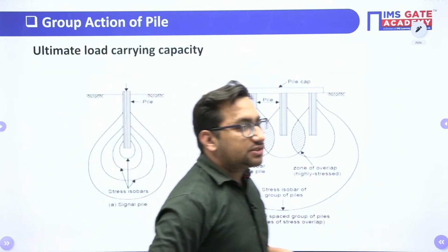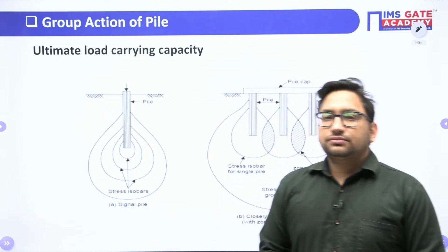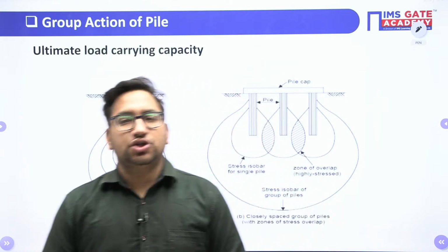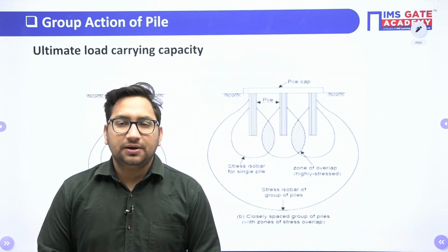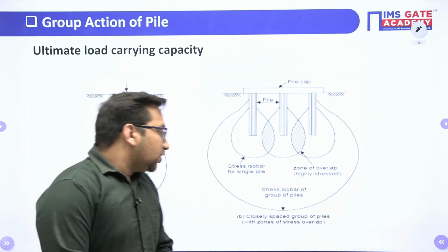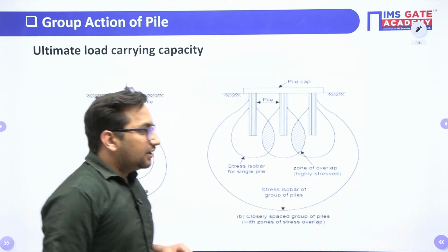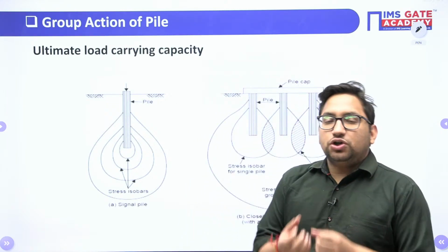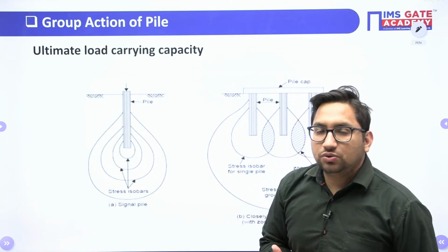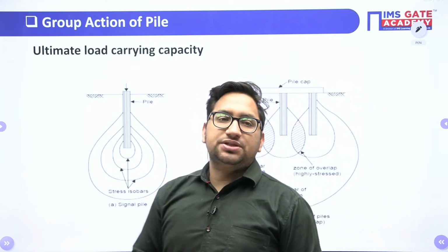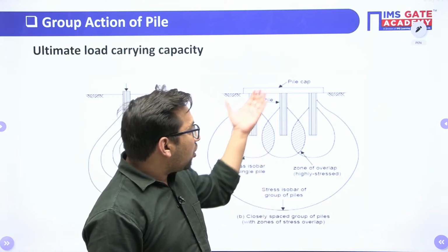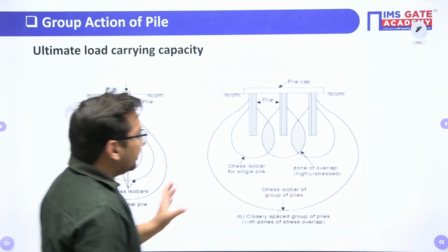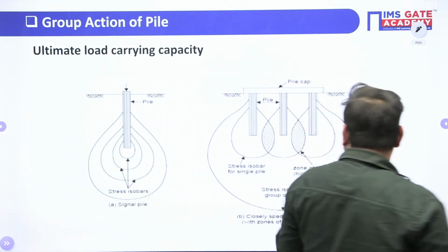Next important concept is group action of pile. We know that we never use a single pile for our foundation. There will be a number of piles or groups of piles. Now, if you multiply the total load carrying capacity of a single pile with the total number of piles, you will not get the same load carrying capacity as when you take all the piles as a single unit and calculate the load carrying capacity. As we know, when the spacing between these piles